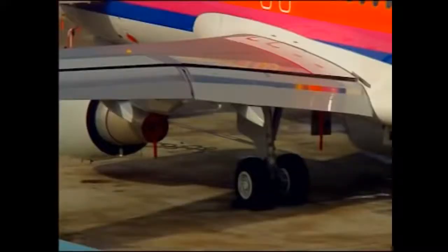Warning: put the safety devices and the warning notices in position before you start a task on or near the flight controls, the flight control surfaces, the landing gear and the related doors, any components that move. Make sure that the ground safety locks are in position on the landing gear.